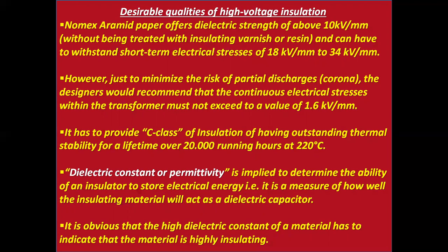Nomex Aramid paper offers dielectric strength of above 10 kV per millimeter without being treated with insulating varnish or resin, and can withstand short-term electrical stresses of 18 kV per millimeter to 34 kV per millimeter.